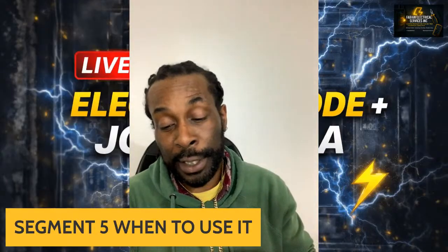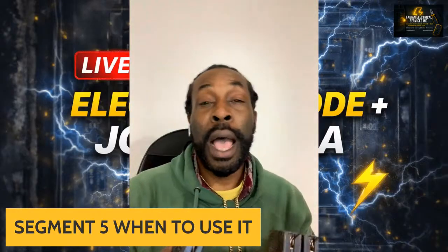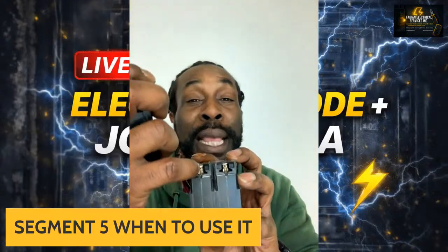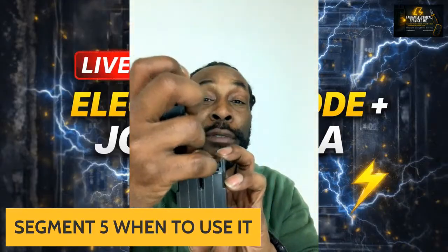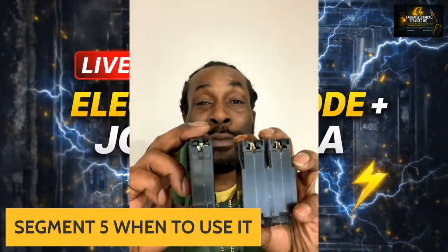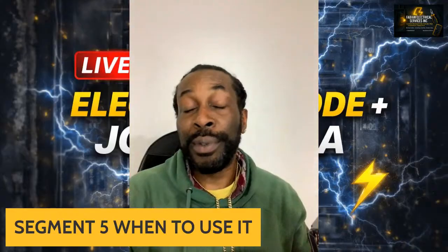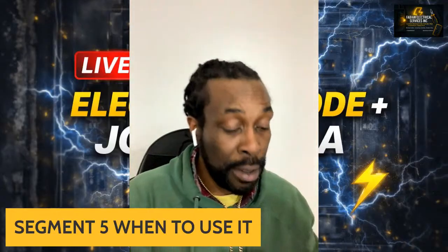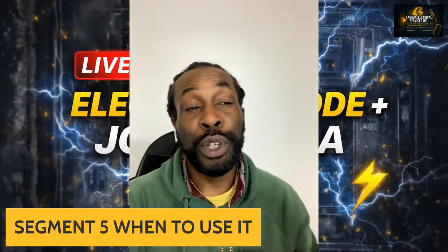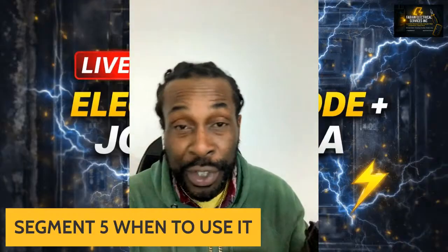And this probably wouldn't go into the panel anyway, because as you can see, there are blades here that are quite different to here. They are totally different to each other. But there are some breakers, for instance, the Eaton panel and the Siemens breakers, which you can use in the other panel, and vice versa.